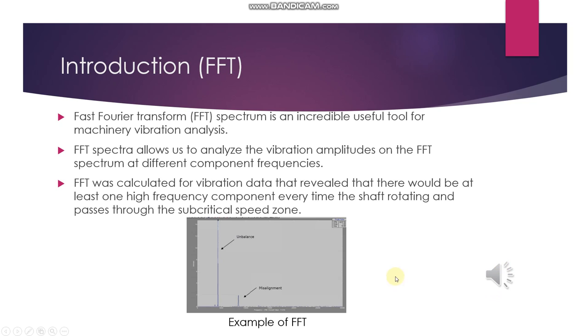Okay, the vibration data is acquired through accelerometers, analyzed using FFT and power spectrum density.